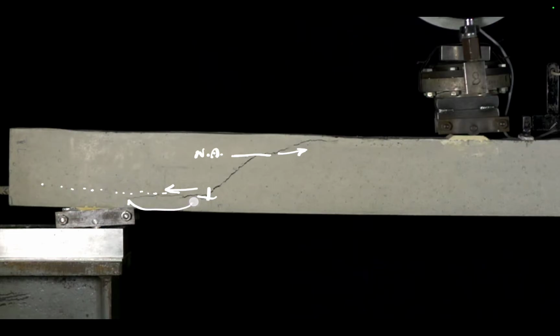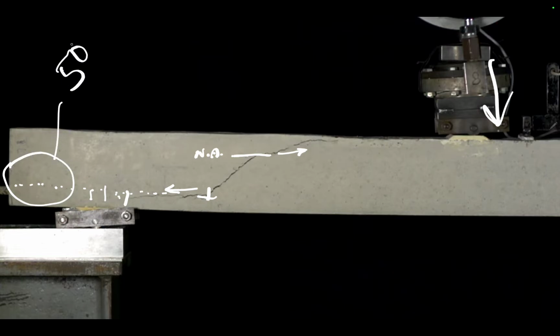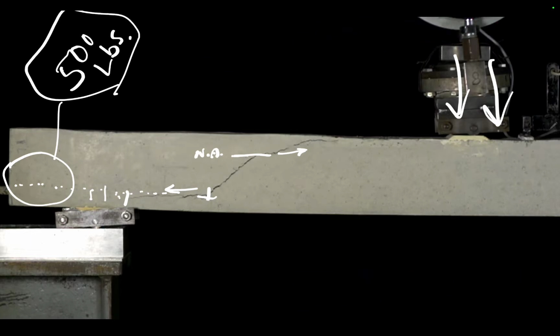It's already separating. Now, let's go to the path to the left. And you see now there's the axis. Now it's got to be taken up by the rebar. That's the connection of this here. And then again, and then again. But this thing is applying a load still. So at one point it's like, I got the last remaining part. The remainder balance might, let's say, take something like 500 pounds of force to break it free. This has got so much kinetic energy in it. Maybe it's got 2,800 pounds of force at this point. When this gets to this point, it snaps off. Flips, this rotates down, flexes down, because it's steel. Remember, steel's inside there. So it flexes, right there, there's our point.